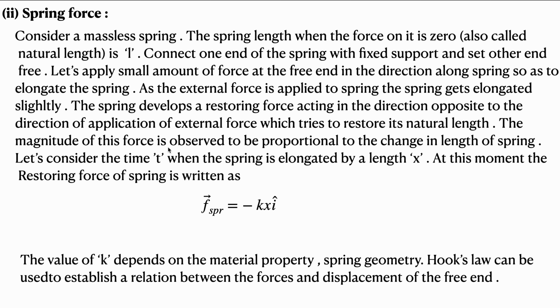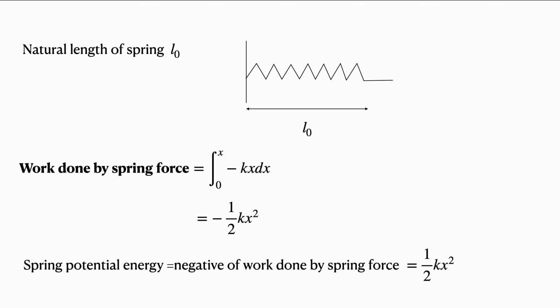The magnitude of this force is observed to be proportional to the change in length of the spring. Let's consider the time t when the spring is elongated by a length x. At this moment, the restoring force of the spring is written as vector F spring equals minus kx i cap. The value of k depends on the material property and spring geometry, and only these two things. Hooke's law can be used to establish a relation between the force and displacement of the free end.